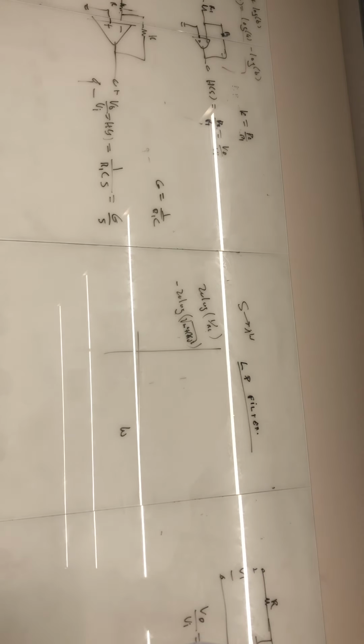Since s is j omega and you square it, wouldn't that be minus? Now you don't square the j. Remember, you got a real and imaginary part in magnitude. Take a look at this. You've got a real a, and then you got j omega. We want this magnitude. You take this and square it, take omega and square it. We want this magnitude right there, because of orthogonal. And actually, the way I'm doing this, I think he's saying because j squared is negative one. There is no j squared. I want the magnitude, I'm letting s become j omega, right?